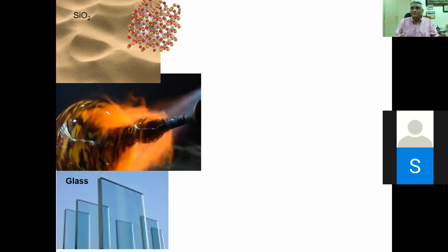So you take the material in a polycrystalline form and just take it to its melting point. So you have it in a bowl or a crucible. This crucible is taken to the melting point of the material. So you see the melt of the material. And if the melt is rapidly cooled to room temperature, that's it. It forms into a glass. So the term glass means non-crystalline, amorphous. That means the glassy form has no crystallinity. That's the meaning of glass. Glass doesn't mean, as I told you, the glass that we use in our day-to-day lives, right? Glass means non-crystalline, because we can't afford to have these window glasses made of crystalline silicon dioxide. Because that process is a long process and it's very expensive.